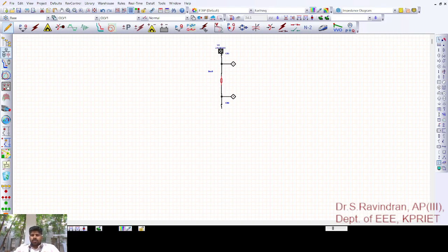So now this transmission line transfers power from the grid to a system. Then the system should have a bus, a receiving bus. Okay, so now this is given to us as a bus. See, when I connect the bus, it automatically takes the voltage 230 kV, because I have given this grid as 230 kV.